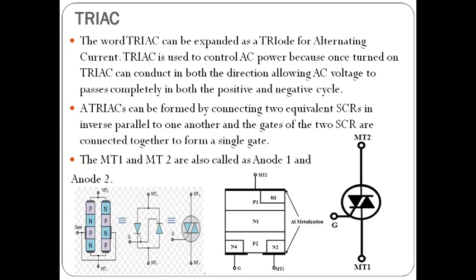Yes. So we are having P and PN, P and PN, two silicon control rectifiers that are connected in the anti-parallel. So P and N-type material of two SCRs are connected as MT2, and N and P-type materials are connected to the MT1.